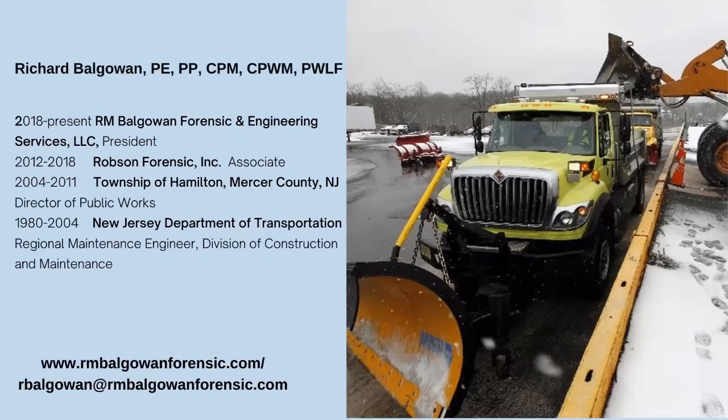And then there are also poor man's things that you can do to measure those types of things, using things like digital refractometers to measure the salinity of any brine solution that might be on the roadway. So there are many, many ways to reduce the over application of salt on a roadway. Much of it involves just educating the workers, educating the supervisors and managers in the individual government agencies or even contractors.